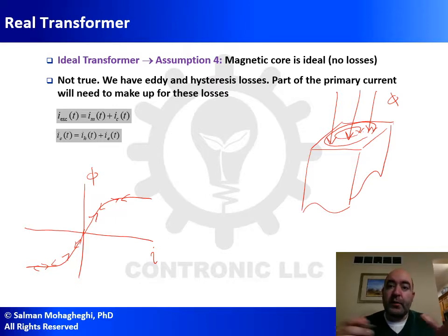But what is the hysteresis effect? Let's go back to the magnetic dipoles. I will start from a random distribution of magnetic dipoles, which, let's say, gives me zero magnetic flux. We all agree with that. But as I increase the current, and I get to some point, let's say this point A, which is the maximum current and maximum flux. If I start reducing the voltage and the current, the flux is going to reduce, obviously, because all the magnetic dipoles will try to change their alignment. However, can I really assume that I start from random distribution, go to all aligned, and once I reduce the voltage, I go back from all of them aligned to exactly the same random distribution? Well, this is not reasonable. I will go to some other random distribution, but definitely not the original one if it was truly random.